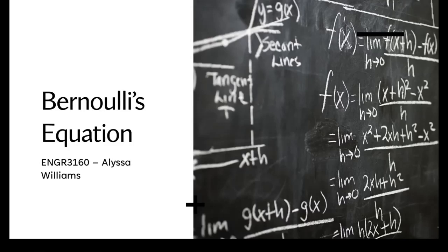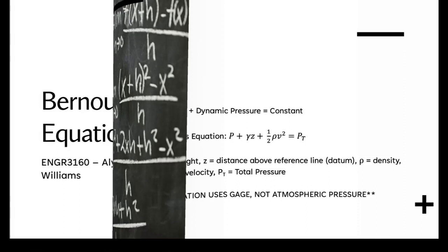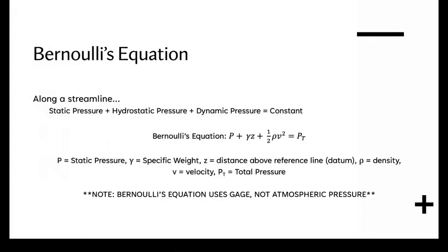Today, we'll be talking about Bernoulli's equation, which is an important concept in fluid mechanics. So what Bernoulli's equation states is that along a streamline, the sum of all of the pressure, which includes static pressure, hydrostatic pressure, and dynamic pressure, is constant along a streamline.